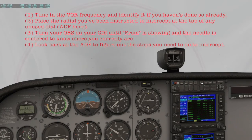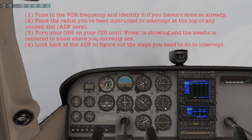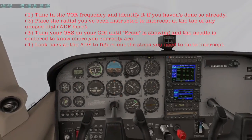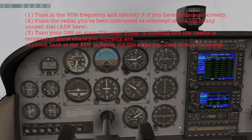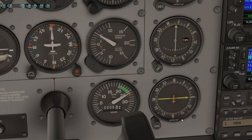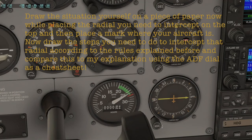And once you're done with these very initial steps that have to be done pretty much every time, what you're going to do is find out where you are and put the radial that you've been instructed to intercept, whether it's inbound or outbound by ATC, on top on your ADF dial right here. We've been instructed to intercept 300 inbound. So I'm going to put 300 on the top right here. This doesn't mean anything. This is just like a cheat sheet. I'm going to use it to find out where I'm at and where I need to go.